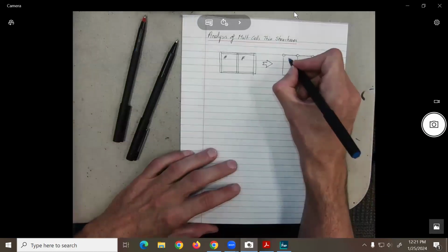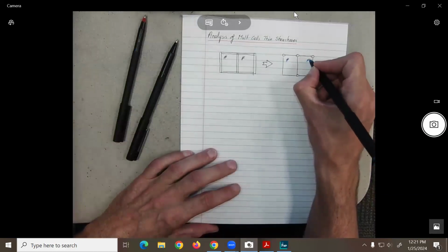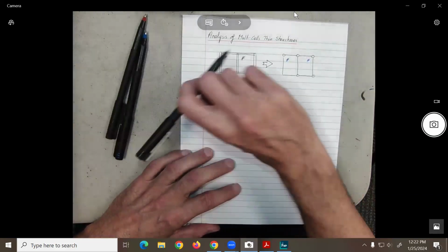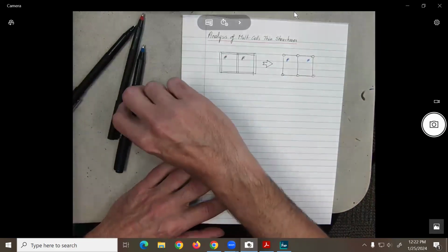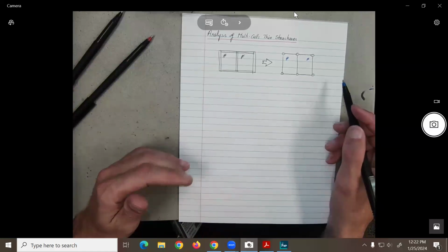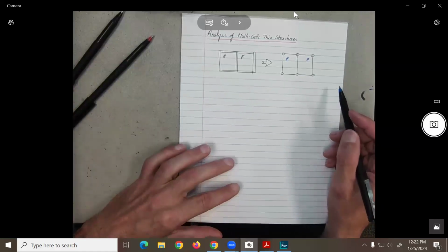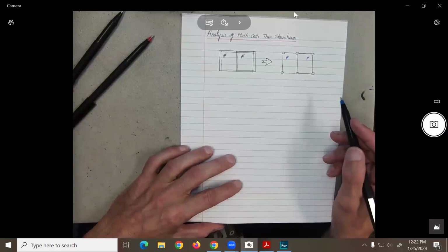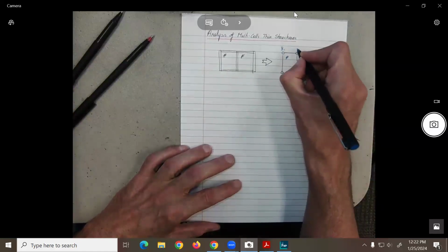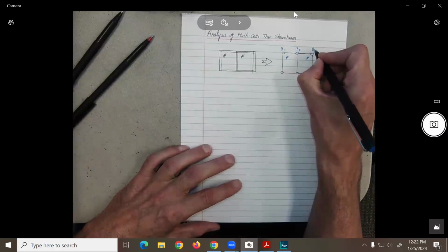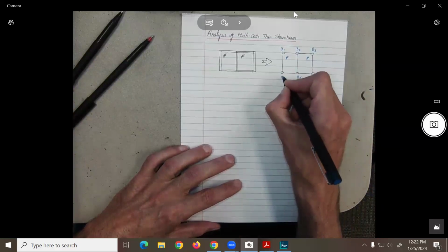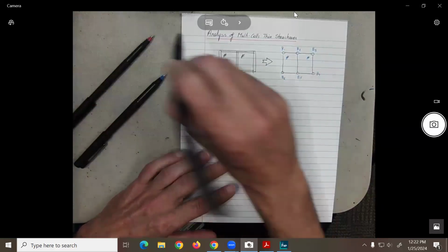So personally, where here you have the panels, you still have the panels. And something different that I do from other faculties, because I use the English notation instead of the other notation, basically, instead of talking about areas, I talk about booms, areas. So basically, you can replace this one by, let's say B1, B2, B3, B4, B5, B6.